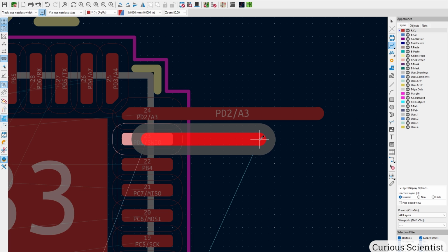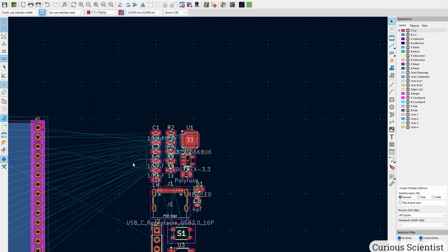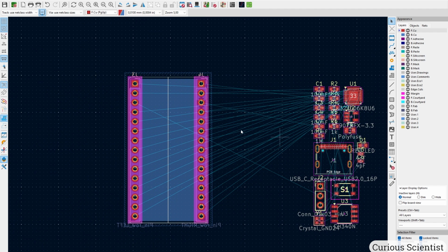So this is very important with this QFN32 package, or any package which has this, let's say, tight spacing of pins. The pitch here is 0.4 millimeters, so we have to have small clearances allowed here, so we can bring out the traces from the individual pins, even the adjacent pins. But back to the board, we can now start placing components.